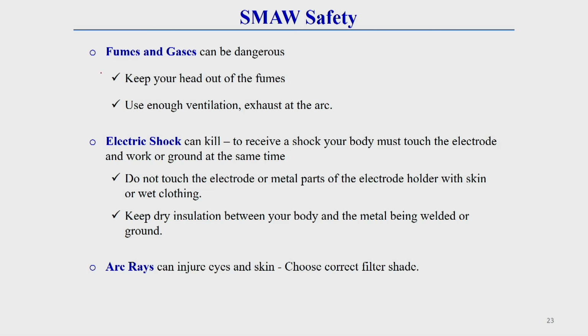So this is one safety precaution, that means keep your head away from the fumes or gases. Then the second one, electric shock. Here there can be chances of electric shock, because if your bare body touches the electrode and workpiece at a time, then a sudden shock can occur, which can be dangerous to the welder. So don't touch the electrode or metal part of the electrode holder with skin or wet clothing. You should keep this in mind. Keep dry insulation between your body and metal being welded or ground. So dry insulation should be there.